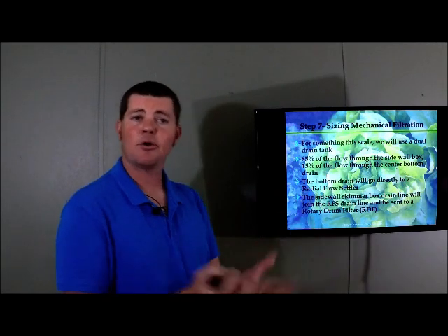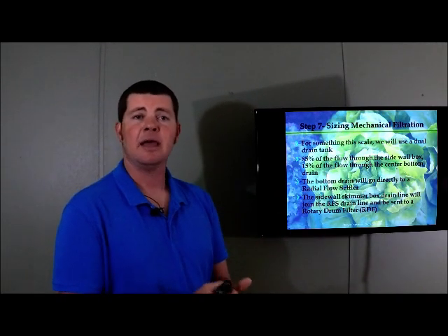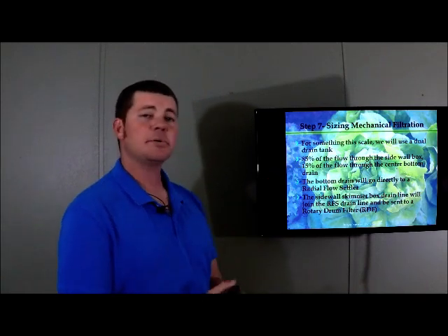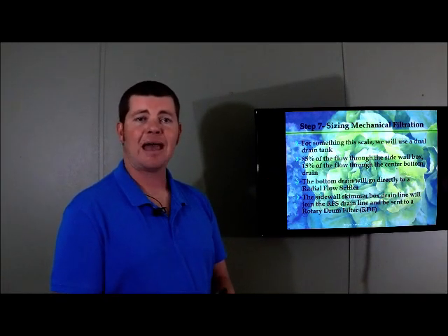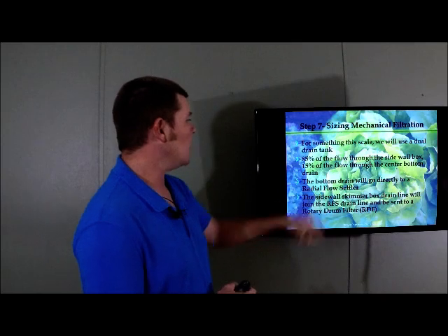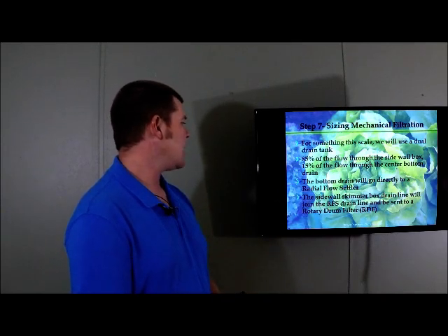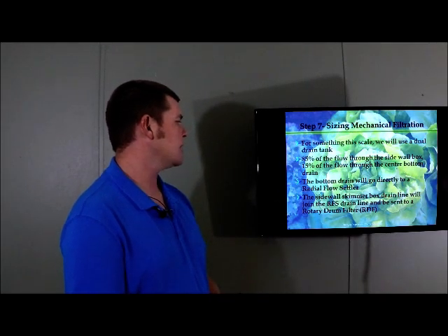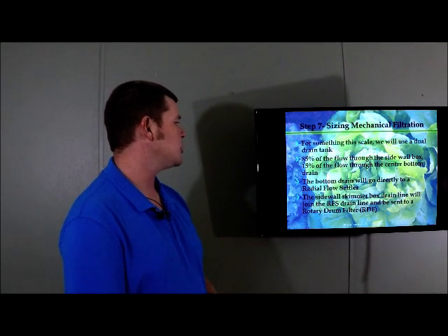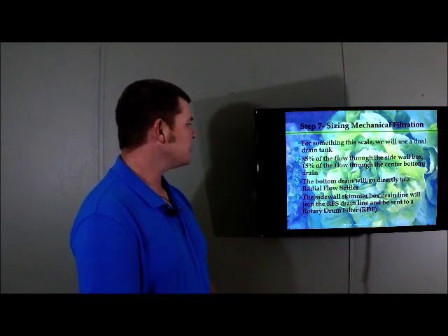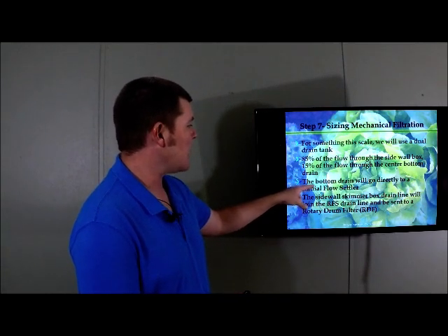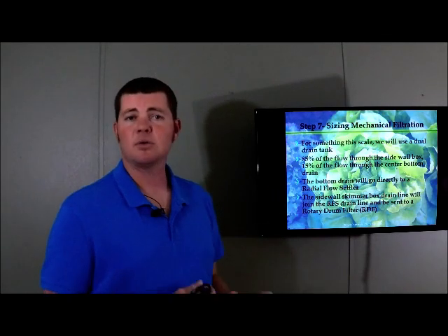All the solids are still going to go out of that center bottom drain, even though only 15% of the water flow is exiting through that hole. The sidewall skimmer box and drain line will join the radial flow settler drain line and be sent to a rotary drum filter. Okay? So after your bottom drain line goes through the radial flow settler and pulls out